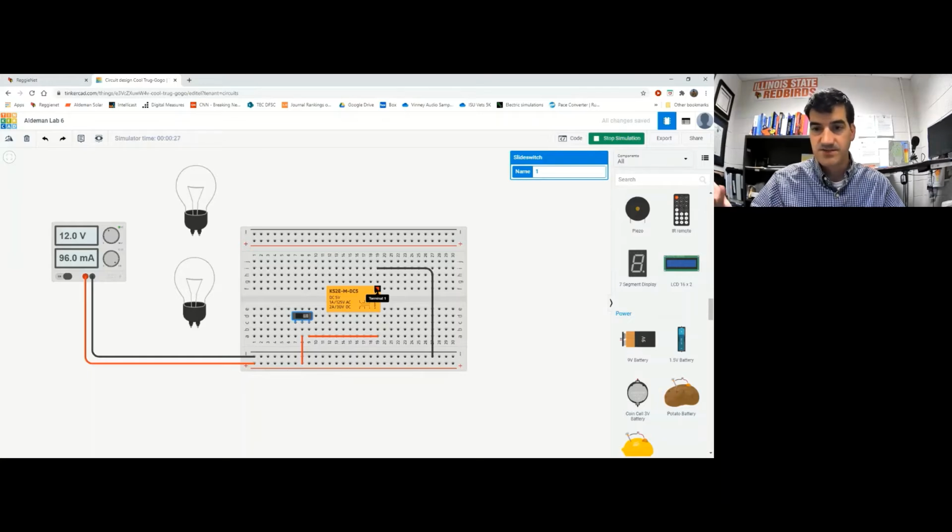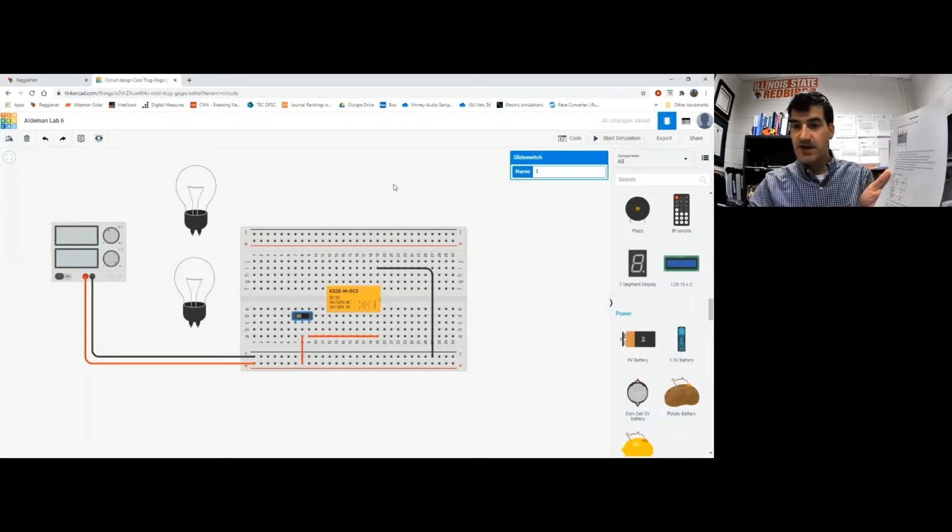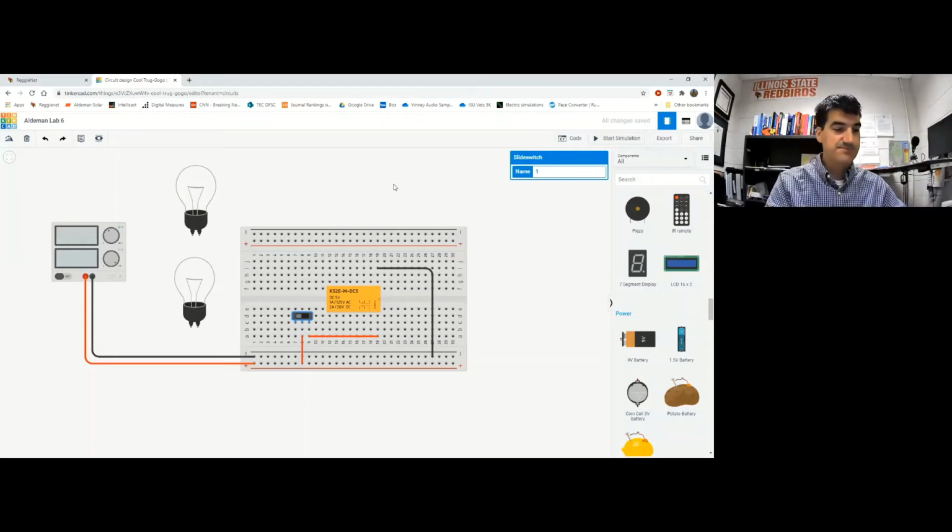And so I get some measurable current going through there. I have a complete circuit, so I get some current going through there. It has a finite value of resistance as well, so it's not an infinite amount of current. But I do measure some amount of current going through there. I can see that right here from the power supply. So it looks good so far. And then if I switch this back, I should get zero current, because this is an open circuit because there's no connection to this terminal right here. Okay, so far so good. I think the top rung of my ladder electrical diagram is good, it looks like.